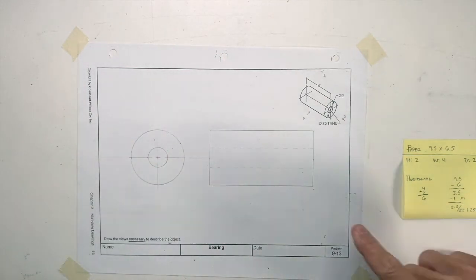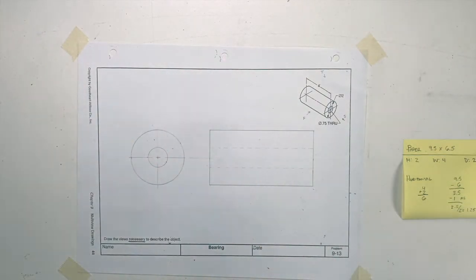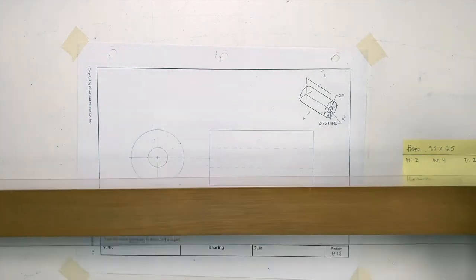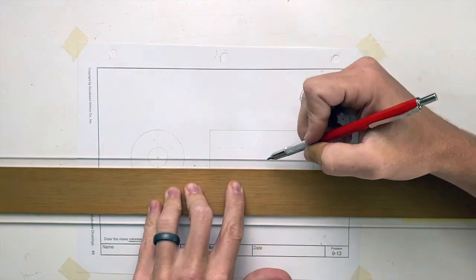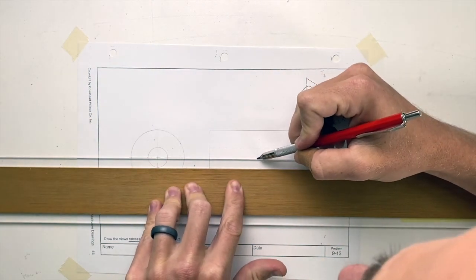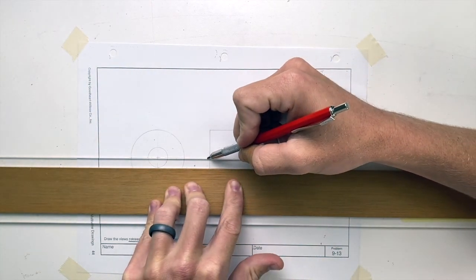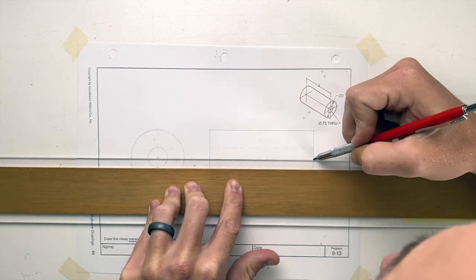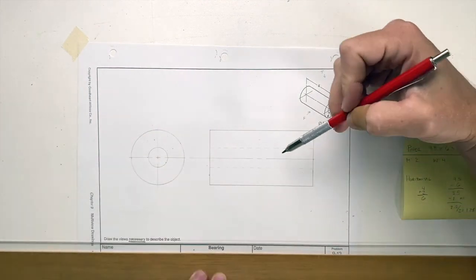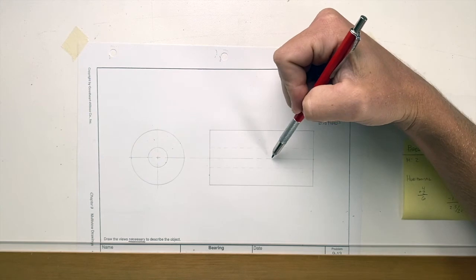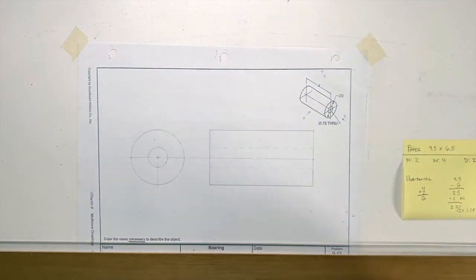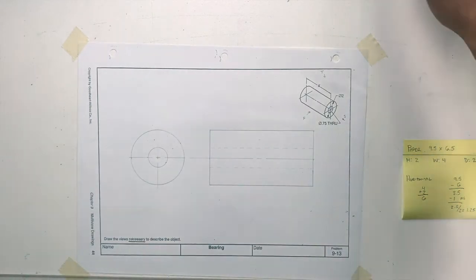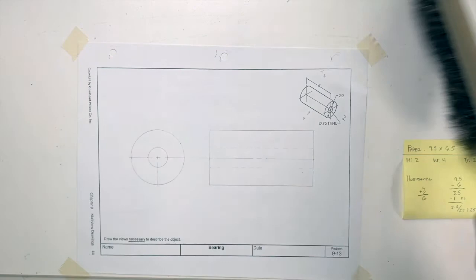And then I should also have a center line that goes through the axes of my side view of my cylinder. So I'd have a short dash right in the middle, and it would extend out beyond the edge of my cylinder walls. So long dash, short dash, long dash, and you can actually connect them, or they should connect because it's the same circle or the same axes through both views. Look to see if there's anything else to clean up on your drawing. And this one's complete.